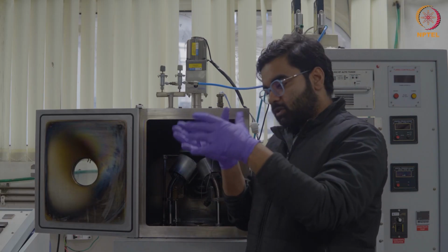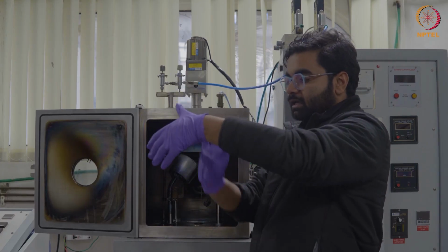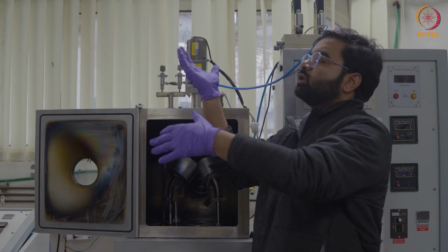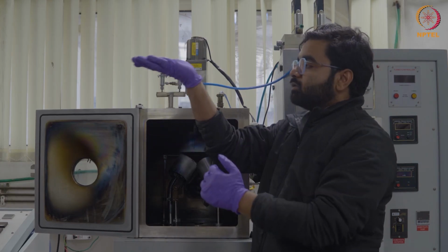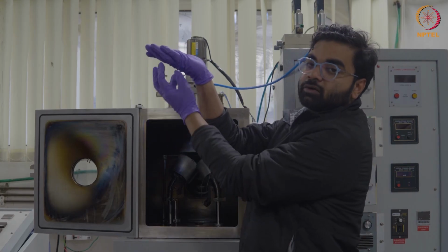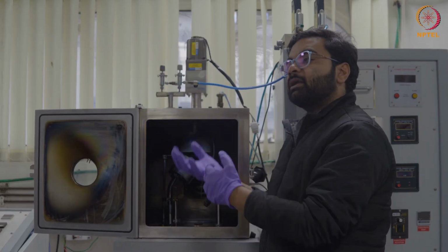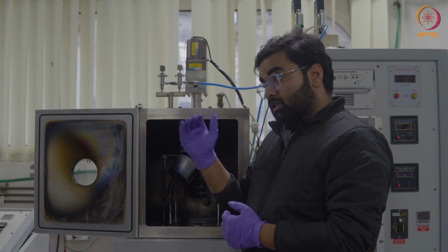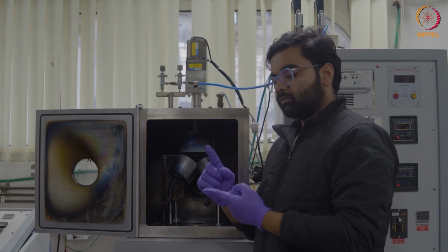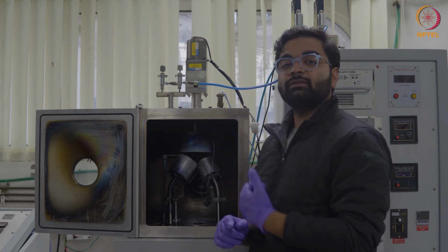This is that plasma zone in which the material is ejecting from the donor, from the target, and then it is coming out and slowly getting deposited on the top surface, which is continuously rotating. So the material comes out and slowly it gets deposited over here. So it's like atom by atom deposition, and because of that, it gives certain advantages. What advantages does it give? The first advantage is the controllability is in your hand.